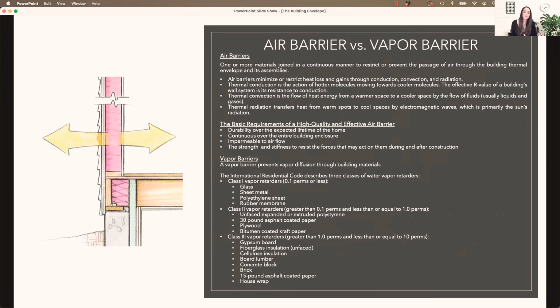So in addition to insulation in buildings, we also want to find ways to keep buildings dry, not only for insulating factors, but also for indoor air quality, which we'll talk about in the coming weeks, and just basically designing healthy spaces in buildings. Wherever water can go or gather, it can cause mold issues or other issues, and can cause decay to stud framing, things like that.